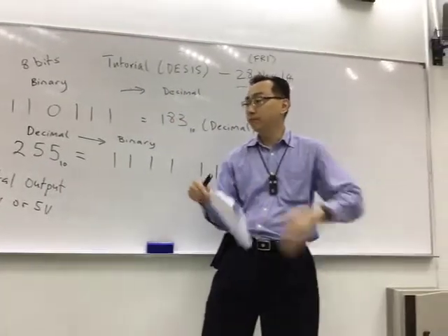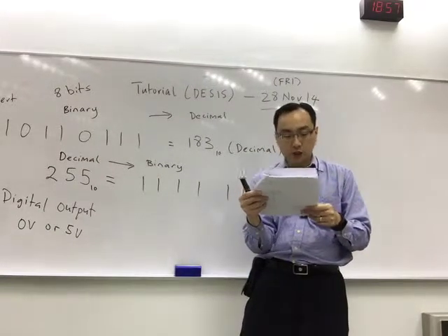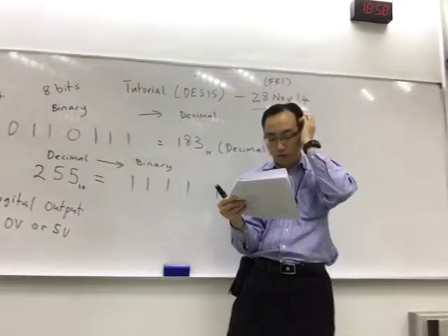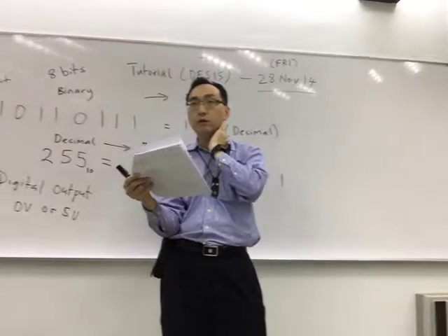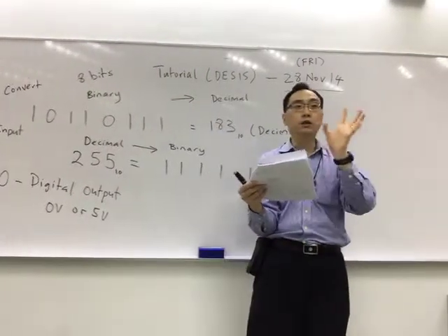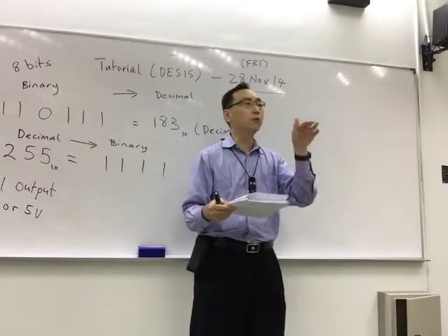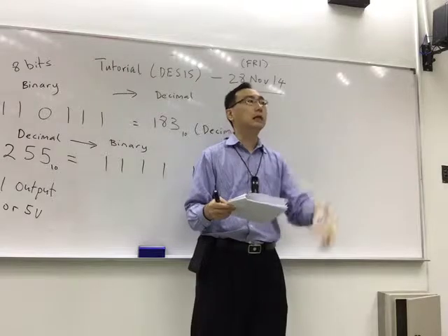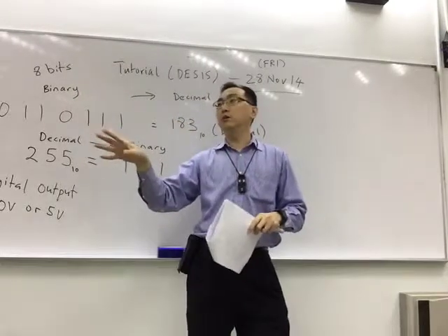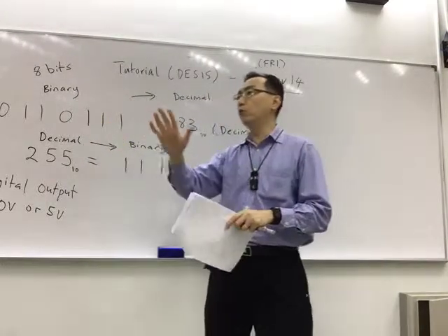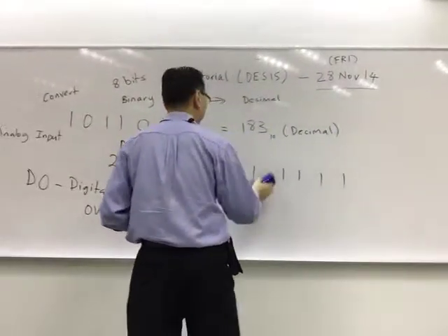Okay, 4 pumps. Now for part 2 of question 6, basically no DAQ. The answer is no, and the DAQ card supplies a maximum of 20 milliampere. Usually the DAQ card cannot supply a lot of current. Usually the output is to drive another circuit. You know what I mean? Your output for your electronics cannot output a lot of current to drive high power. So you have the low voltage and then the high power circuit. It's standard in the industry.